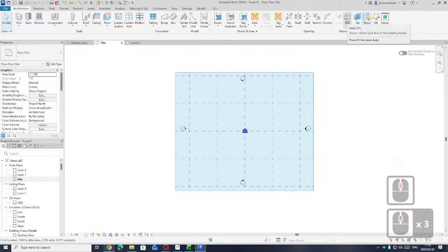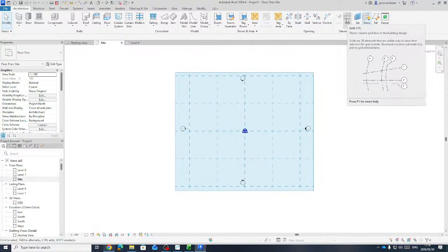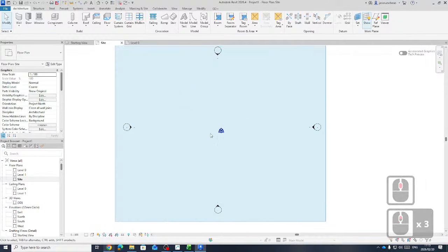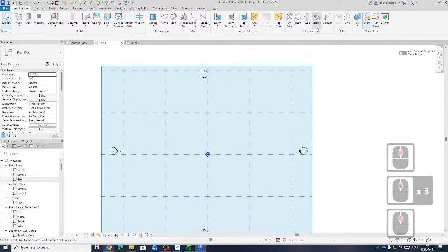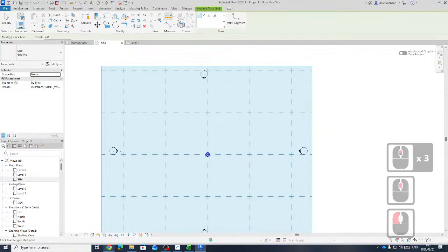The only difference with Revit is that each grid system and level system has a 3D extents, and you might have to drive these by using scope boxes. It's a bit more complicated, but they're very powerful, especially if you've got multiple grid systems. All right, so you can see I've got a guide to work with straight out the bat, so I can start with my grid system.